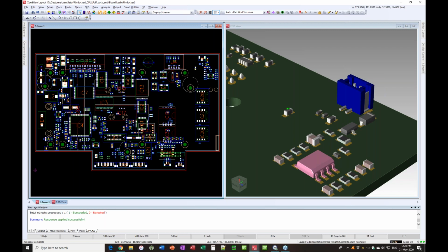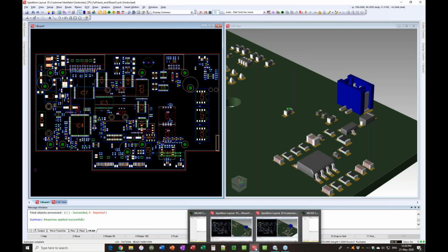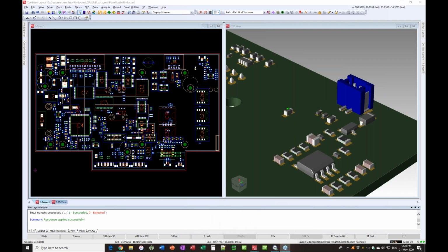Sure. Any thoughts on how this drives simulation once we get this all together, both in the ECAD, MCAD integration? So on the simulation side, from the Mentor side, all of this information in the electrical domain, you can launch simulation tools for signal integrity, power integrity, creepage rules, things like that for safety. And on the Siemens side, you can take that same design data that we passed from ECAD to MCAD, and then those MCAD tools can go into things like Simcenter, launch into thermal, do any other kind of analysis that we can connect to, all integrated based on the same data set.